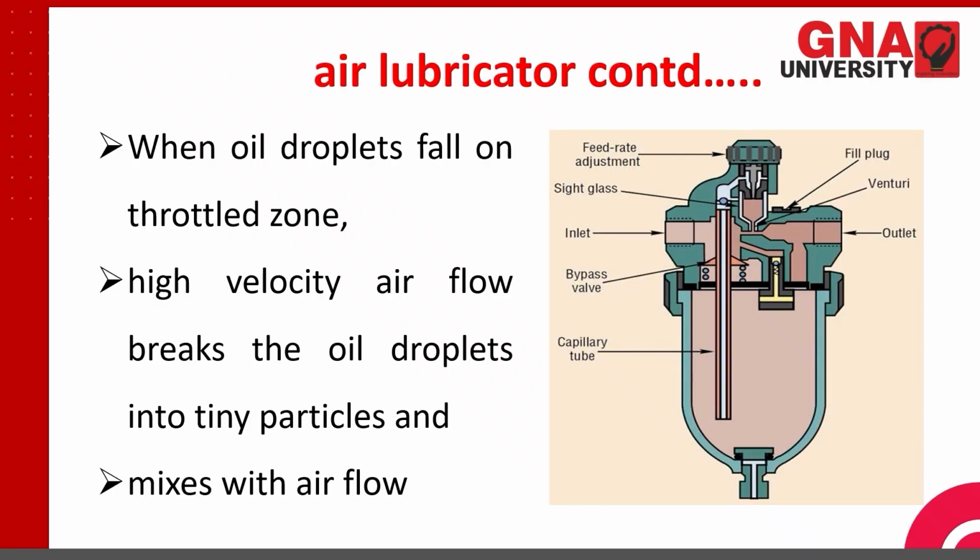That is the third portion, that is the lubricator. So what happens? The compressed air is mixed with the mist of an oil in order to provide lubrication to sliding components. It works on the principle of the Venturi, a fluid mechanics principle you have already studied in your previous semesters. You see this is the principle explained here.